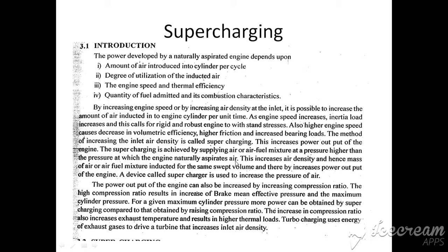An engine naturally aspirates air somewhere around 1 bar or somewhat less than that. Whereas supercharging increases the air density and hence the mass of the air and air fuel mixture inducted for the same swept volume, and thereby increases the power output of the engine. A device called a supercharger is used to increase the pressure of the air.